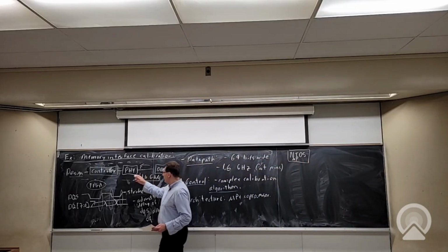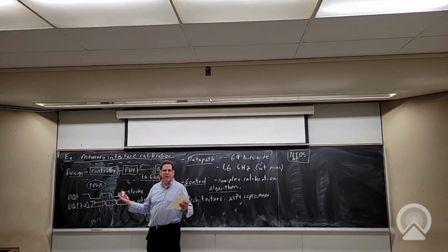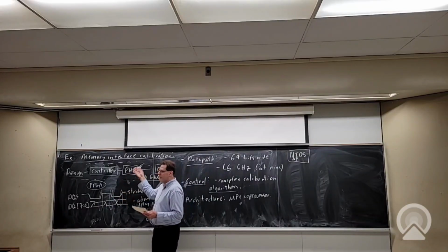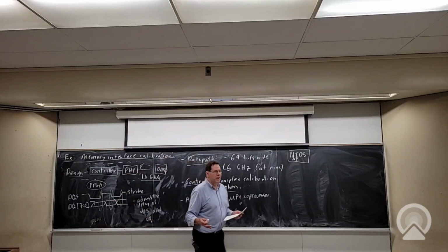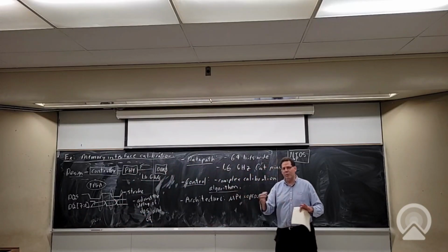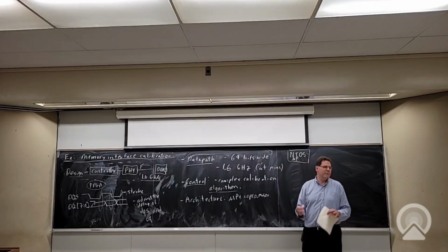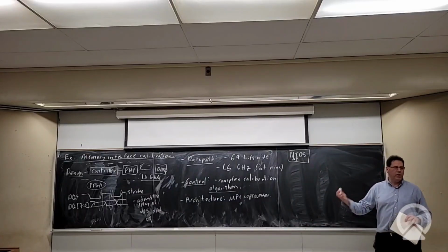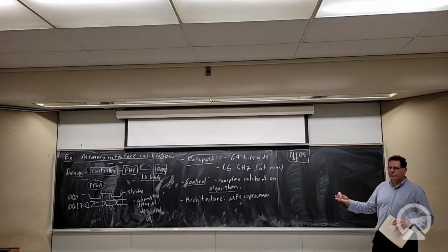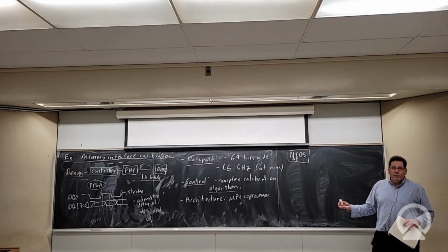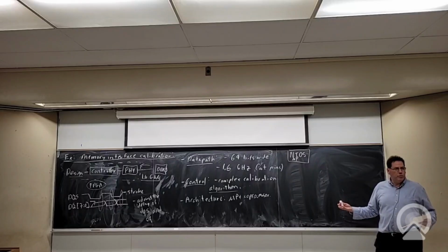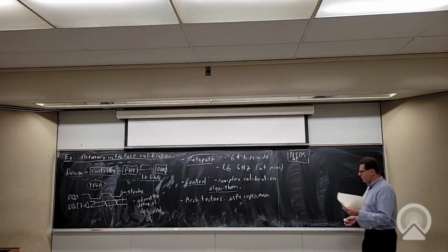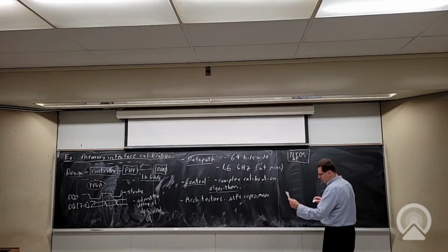So we actually embed one of these. If we have multiple DDR interfaces, so you might have a big design that has 6 DDR interfaces, they each get their own Nios. This is an example where the fact that we can stick these soft processors wherever we want is beneficial, because it's just stuck right in the IP. You want more DDR interfaces, you get more soft processors. If we used the hard processor on the chip for this, first, on most of the Altera chips, there's only 2 of them, so we might run out. They might be in the wrong spot, and it might be noticeable that we stole the hard processor. So it's a good example for making a cheap soft processor.